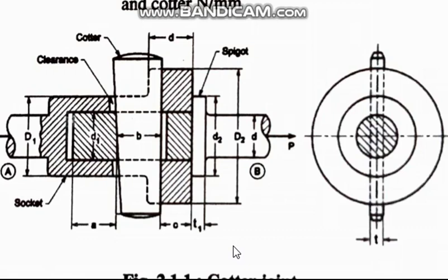And you should be able to draw those areas, and after drawing those areas you should be able to find out the equation of that area. Once you know this, you can put it in the strength equations, and then you can find out the diameters. Finding out the diameters, or the dimensions of the joints, this is called machine design mostly. Most part of it is finding the dimensions only.